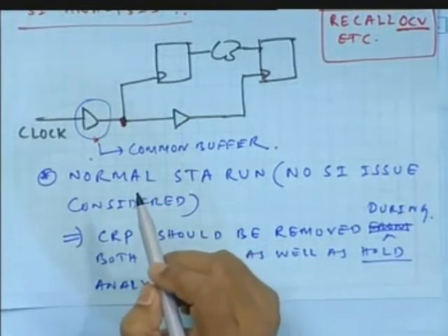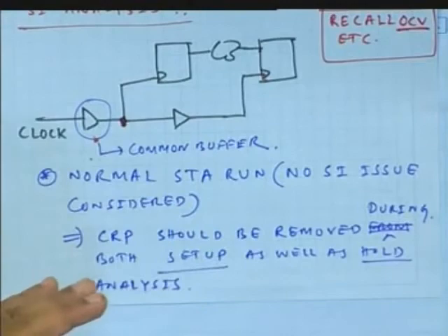The windows: the moment I am getting affected, whether I will be affected after 1 second, same way, it's not guaranteed, right? For setup analysis, which edges do you take? Is it the same edge? It's a different edge. So for setup analysis, the edges are coming at different times, right? The launching edge and capturing edge are different. So the way they might be affected is also different.